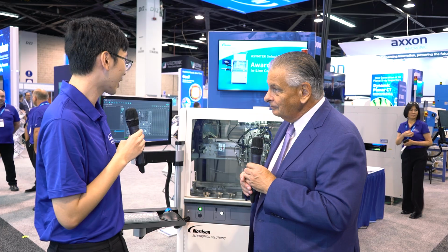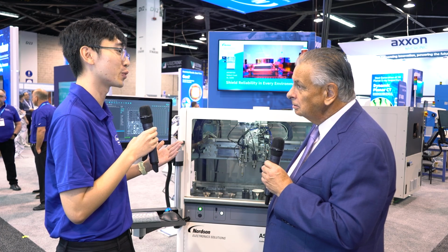Right. So after last year's Apex, as well as some feedback from some other customers, one of the new things we've been working on software-wise is what we call the 3D visualizer. It's essentially a feature that lets customers upload their own 3D CAD files directly into Easycoat to use for offline programming. A big complaint was that we had the 2D image before to help with programming, but we didn't know how tall certain components are. So this will give users that information when they're working offline.